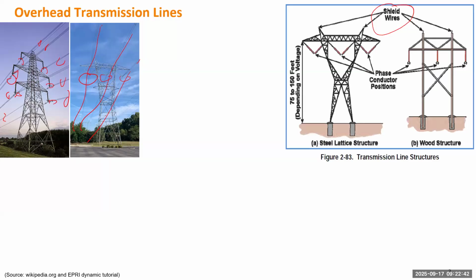They are not delivering electricity over the conductor. They provide a circuit if you have any fault. It will help to protect the transmission line locally. If there's any grounding fault, that shield wire will be functioning. But in most conditions, you only have those 3 transmission lines. So you can recognize which is the shield wire and which is the transmission line by identifying the insulators. And the size of the insulator tells the voltage of the lines.